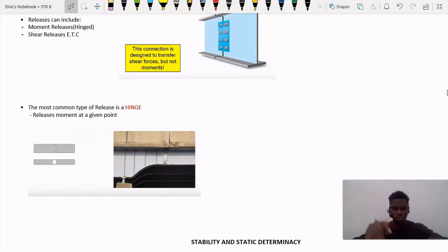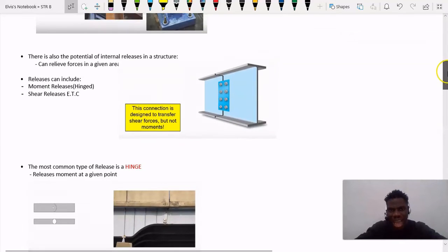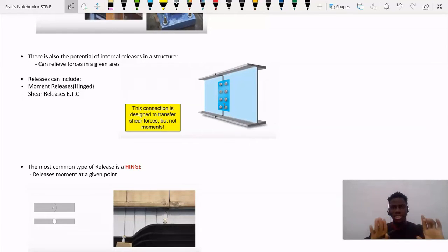So we tend to use what we know as a splice element. That is, we are going to have a series of splices with some plates. This is going to connect the components together. As you can see, guys, this is what I'm talking about. We're having a series of bolts connected on the web.